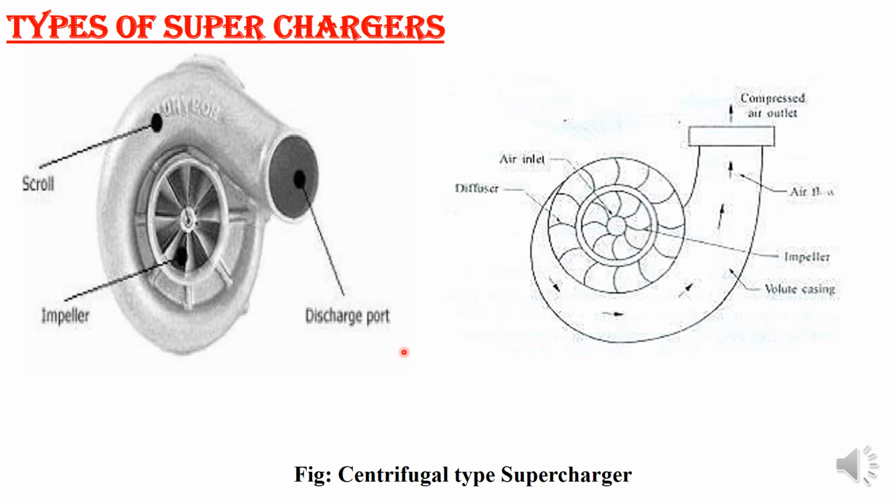Okay, now leave about that one. The compressor can be driven by the engine through gearing. So this can be by the gearing mechanism through the engine crankshaft, or might be exhaust driven, that is a turbocharger. In case of a mechanically driven compressor, a high set of gear is required. Remember, we have to check the proper gear ratio so that it matches the engine speed.